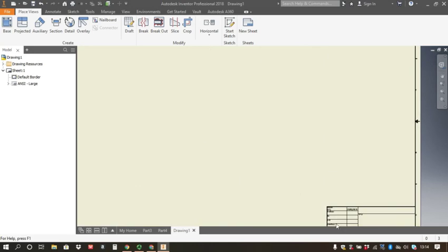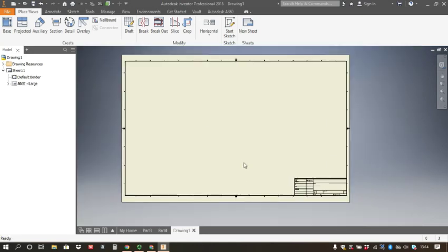The first thing we have to do is actually start to put the drawing down. Now there are two drawing conventions that you can use, first or third angle, but for this I'm just going to show you how to lay out when you need 2 drawings and lay out when you need 3 for the second drawing, and you will choose one or the other as is applicable. Generally for a round object only 2 drawings are needed.